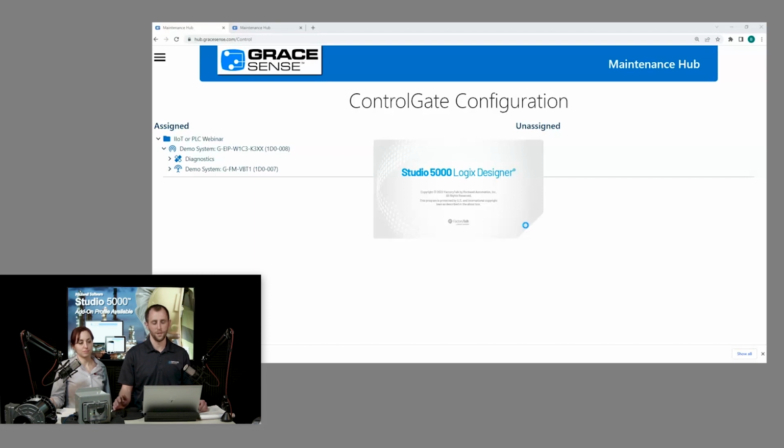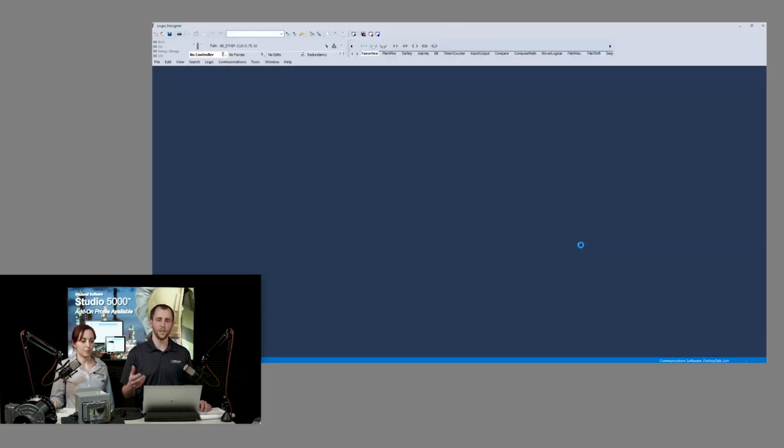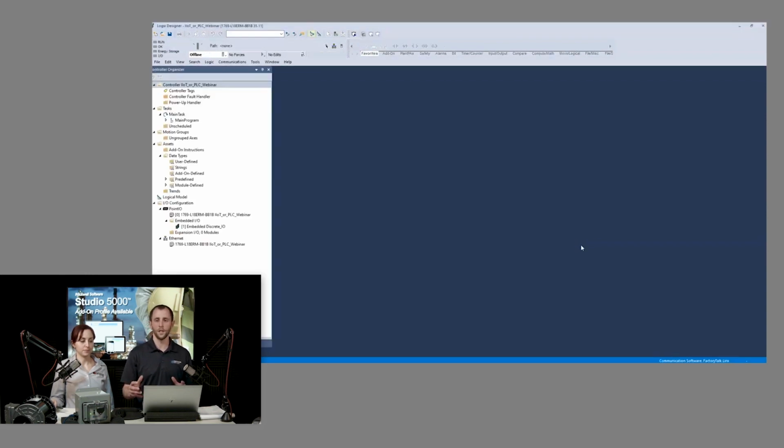So that's very fast. There's a lot of unique things we do with that AOP export that I just did. Our memory map is not a static one. If I add 3 more VBTs to this network, I am going to have a new memory map for that. There are panel mount nodes that let you bring in different types of sensors, like 0 to 10 volt sensors. If you wanted to get a CT, or 4 to 20 milliamps for pressure or flow, you can bring all those sensors in, and it makes a unique memory map that we're able to export as an XML file that we can bring in, so you're not manually mapping all those tags. That's something unique that we did, and why the custom AOP is really an important part of this integration.